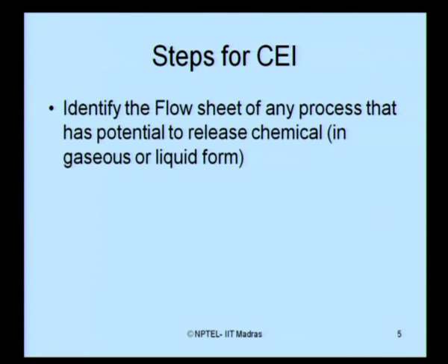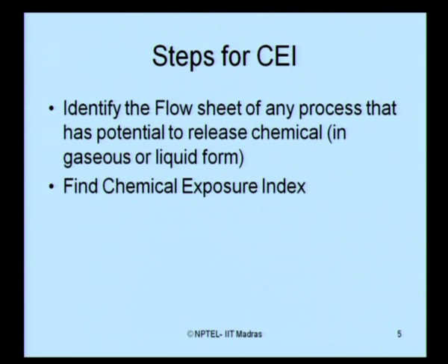What will be the people in operation in such chemical plants, what will be the population of the public in the immediate vicinity of this chemical industry. All data should be available before I start applying the CEI study to any chemical release problem. Once I have that, subsequently I determine what I call the chemical exposure index. So, I will get a quantitative number which converts the toxic dispersion effect of the chemical on human health.